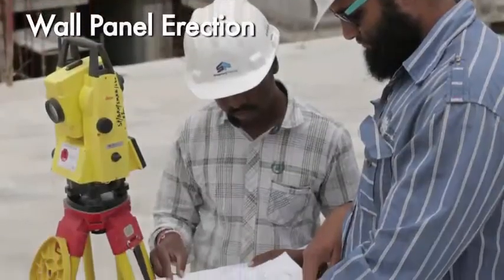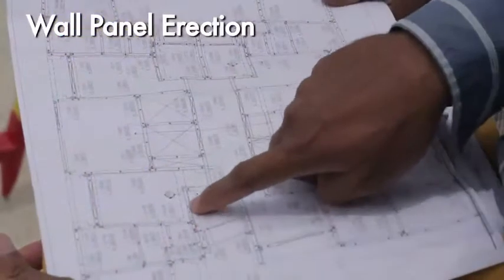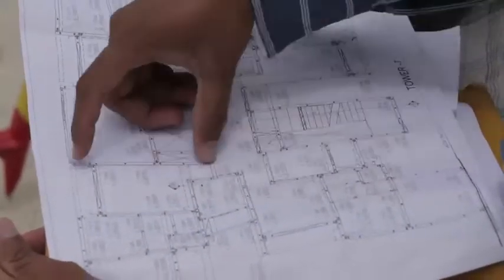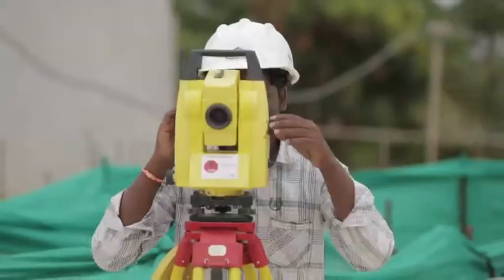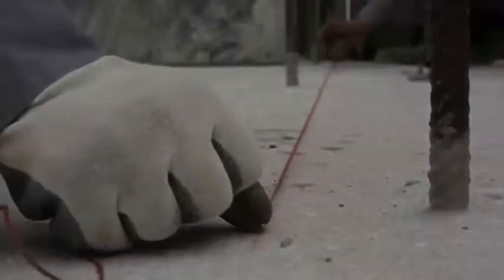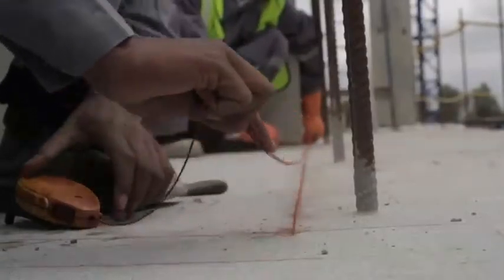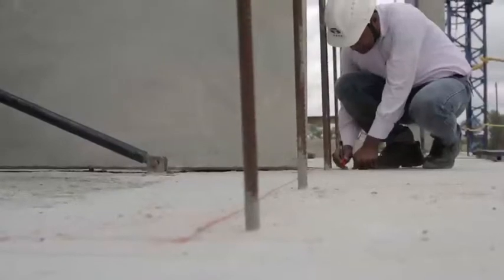Wall panel erection. Coordinate points of the walls are identified on the floor using total station and marked with paint. Later, by using colored chalk and string, wall locations are marked on the floor.